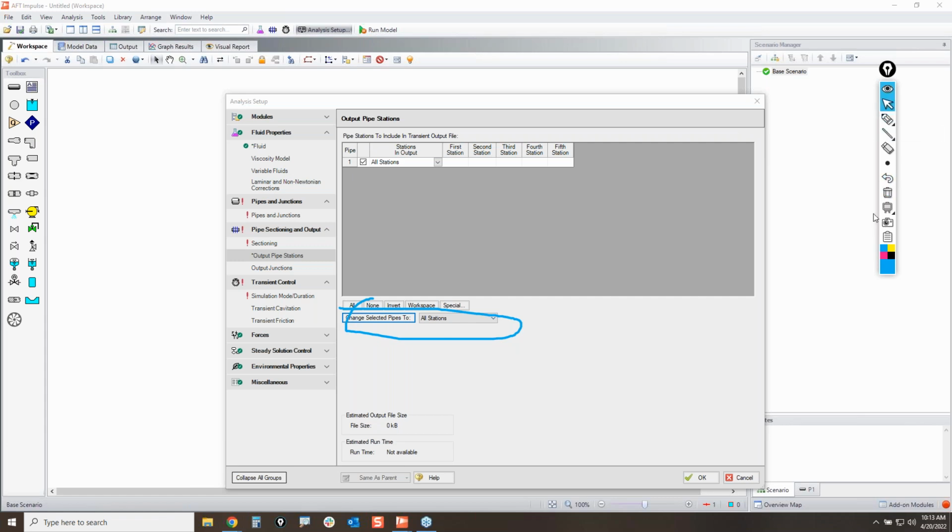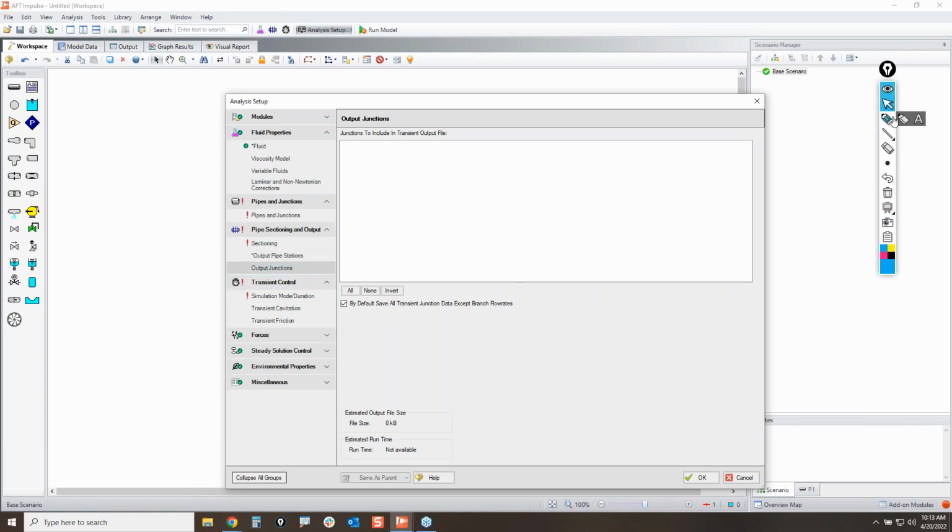So that is something I think is important with that particular window there. You can also choose the junctions to save their output. There's no junctions in this model, obviously, but pumps, valves, control valves, gas accumulators, surge tanks, those are junctions whose results can change over time for their junction-specific parameters, like the pump speed for a pump, and you'd want to be able to plot that versus time. And so this is where you would choose to save your various junction results in that window.